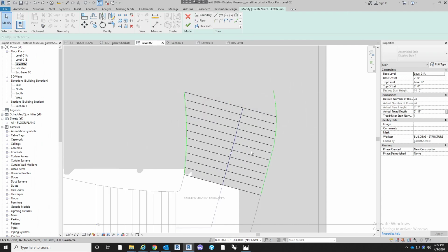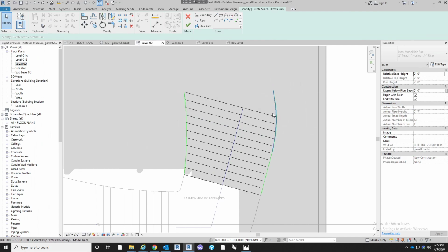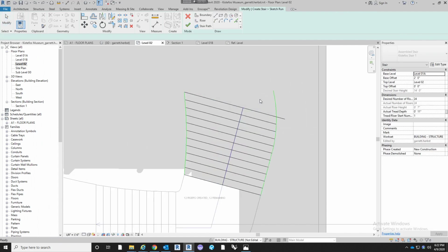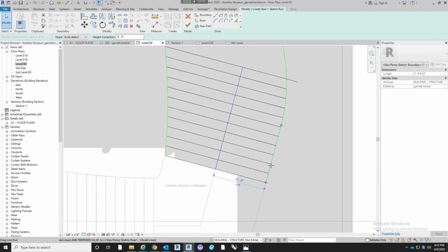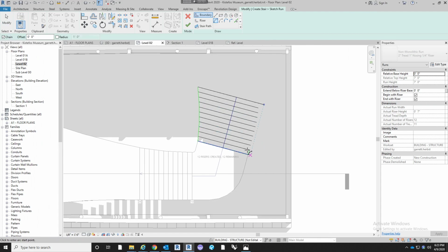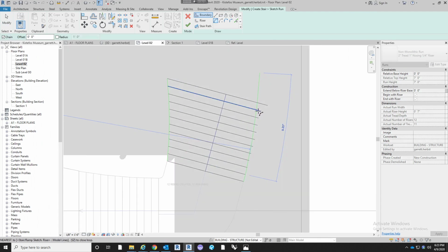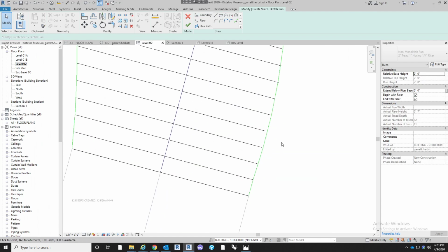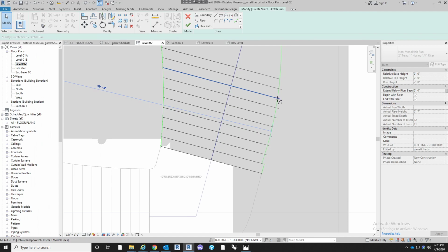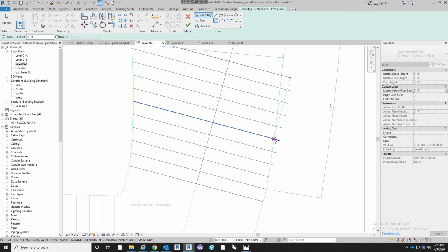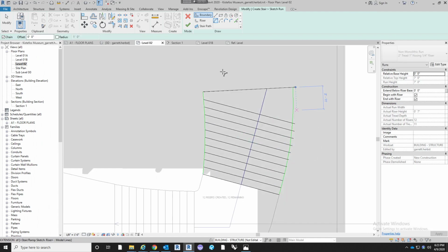See, that works. And as you can see, the boundary of the stair can go past the riser, and actually the riser can go past the stair. I just like to have them kind of matched up. All right, so let's bring this back a little bit further. Let's just have it be straight for one riser, so it stays connected to the landing. Then let's bring this out to where we originally had it. And then let's start bringing those risers out. Actually, let me do that. Let's bring that one riser out. There we go. That's a little better. Trim extend all of these guys.